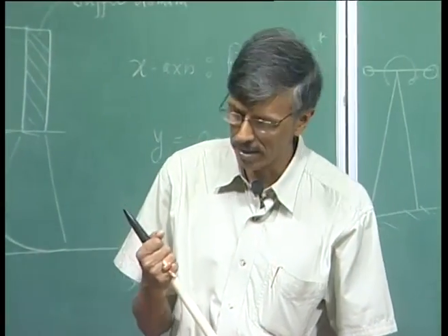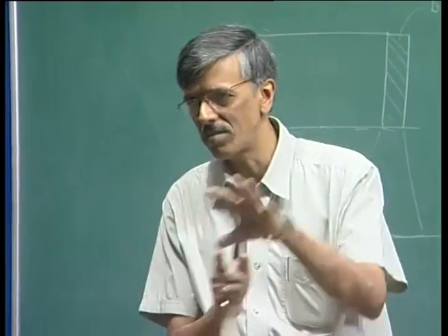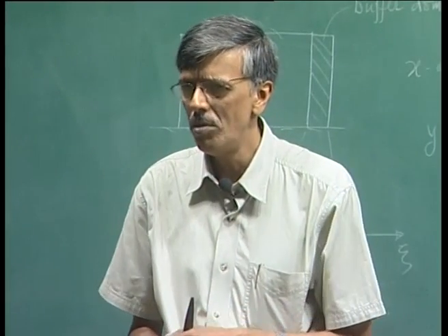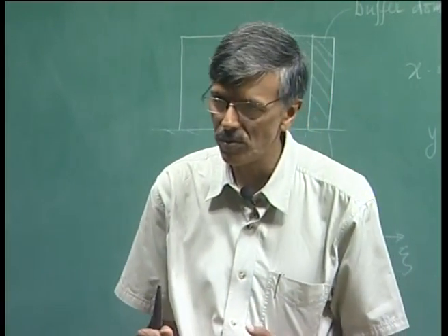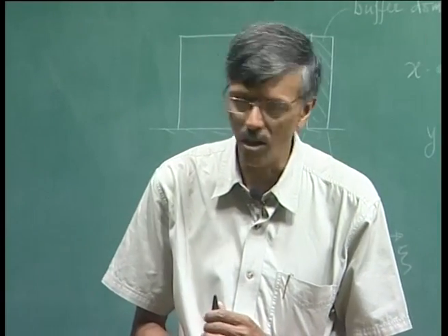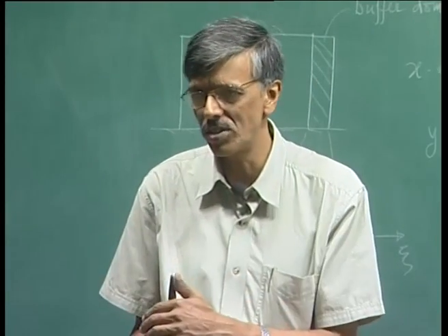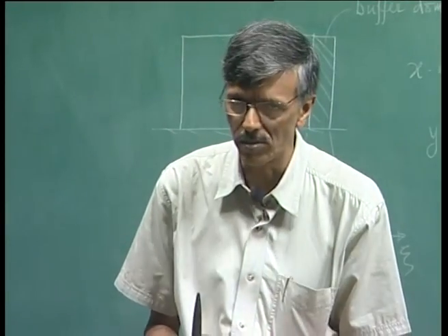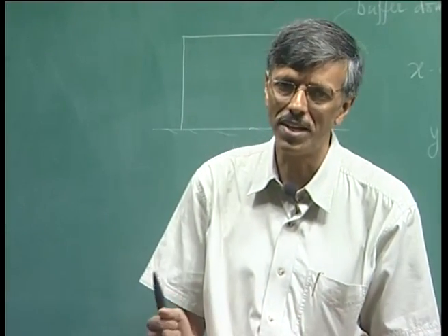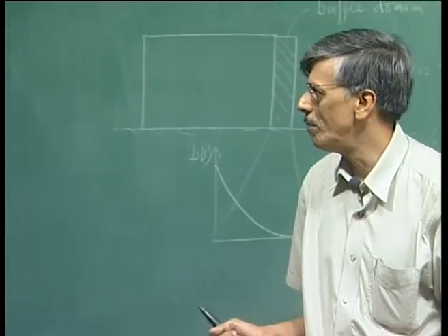And what he meant is that there are all these nice lab experiments where we demonstrate Tollmien-Schlichting waves, but there are many flow situations where Tollmien-Schlichting waves are not at all relevant, and they are undergoing transition due to some other mechanisms. So, all these other mechanisms taken together, he coined as the bypass mechanism.